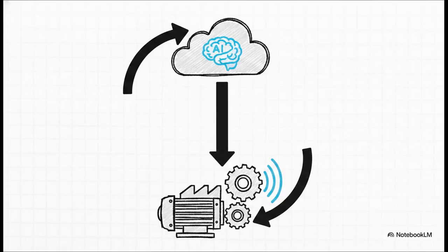And this brilliantly illustrates how that bi-directional capability actually works in practice. Yes, sure, your real-time machine dashboards are updating instantly with that sub-second latency we talked about. But simultaneously, your cloud-trained models in Vertex AI can analyze that data and push optimization commands directly back through MCE to the shop floor. The PLCs receive these commands and adjust automatically. So, for example, instantly modifying an OPC UA motor speed controller based on a real-time cloud calculation, the AI is actually talking back to the machinery.